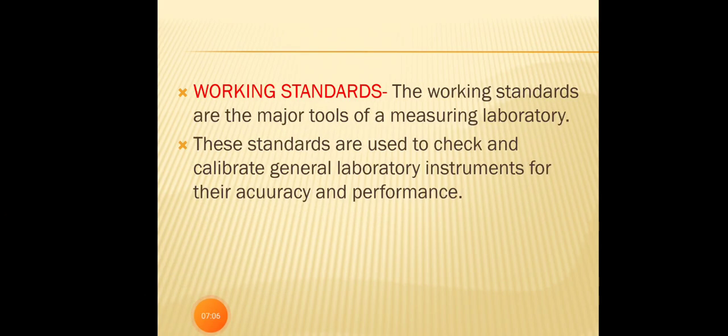Then the working standards. The working standards are the major tools of a measuring laboratory. These standards are used to check and calibrate general laboratory instruments for their accuracy and performance.